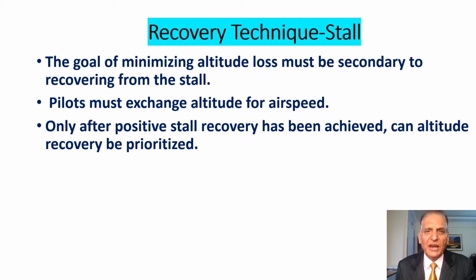The goal of minimizing altitude loss must be secondary to recovering from the stall. Pilots must exchange altitude for airspeed. Only after positive stall recovery has been achieved can altitude recovery be prioritized.